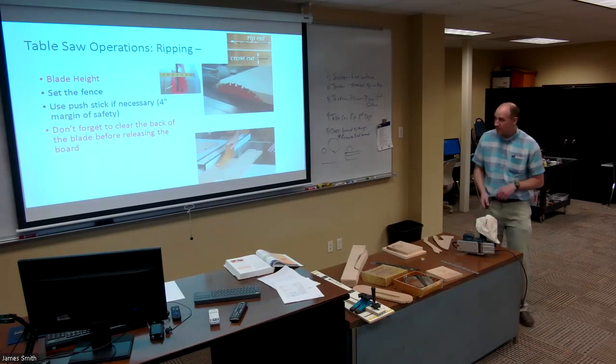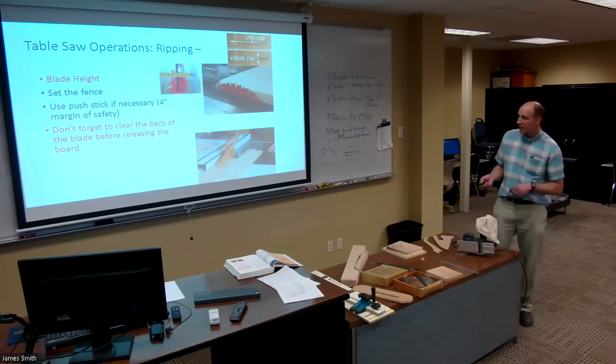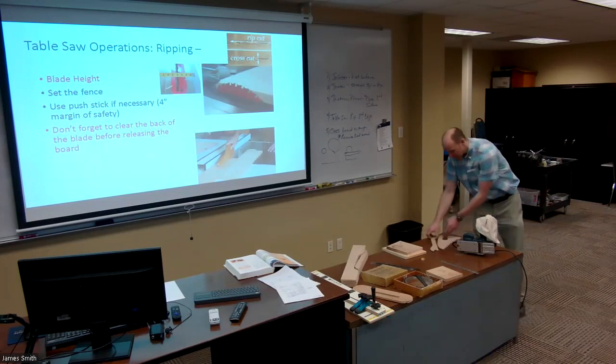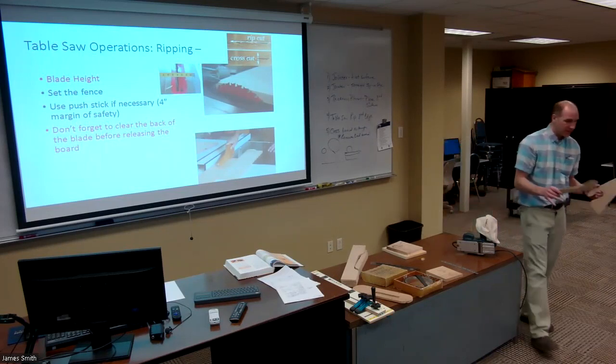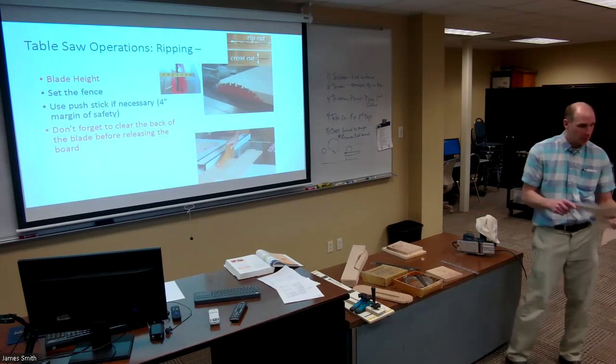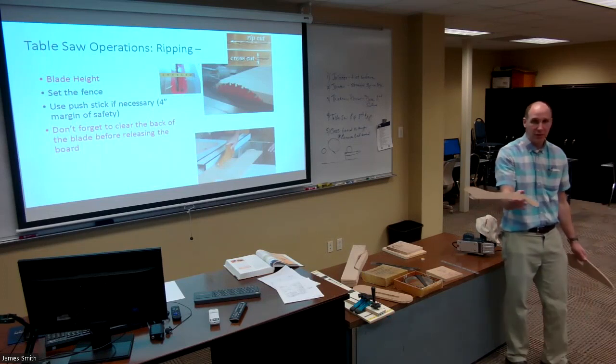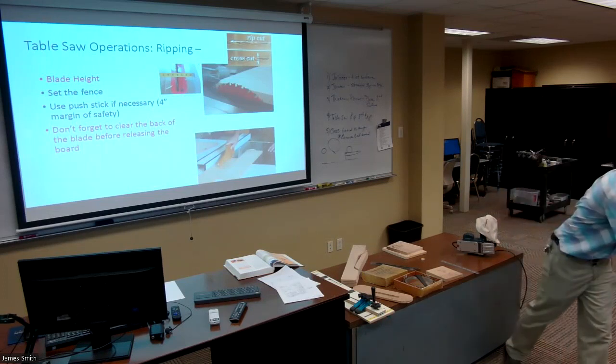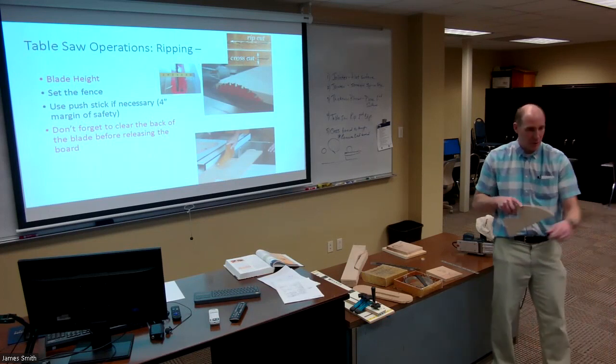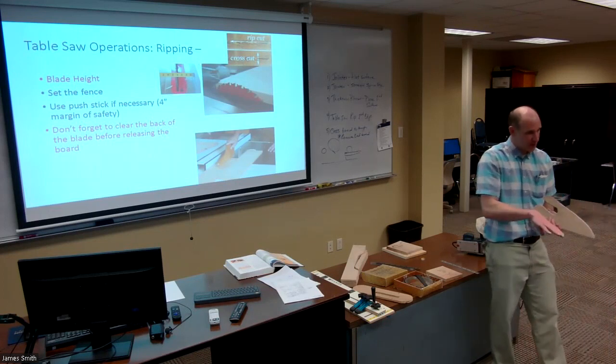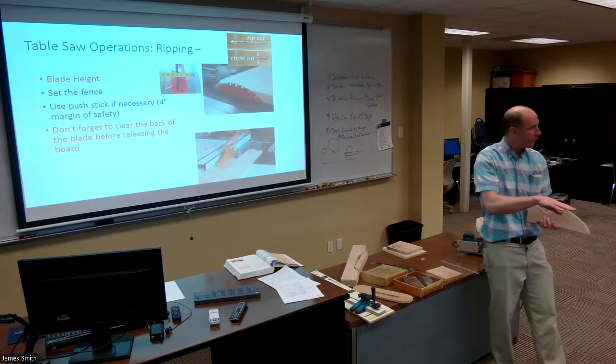Use a push stick if necessary. You can see him using a push stick. I brought a couple of examples of push sticks here. There's different, whatever feels comfortable to you guys. If you're doing long boards, something like this would be a really good push stick. If you've got short boards, you're going to need to put more pressure on it because if you're pushing that into the board, it's going to kind of want to lift on the leading edge.